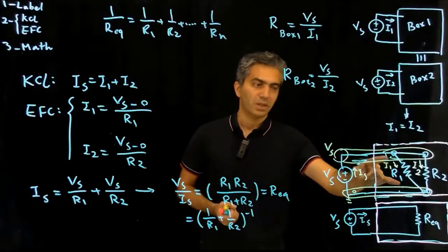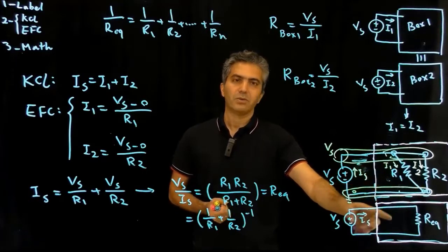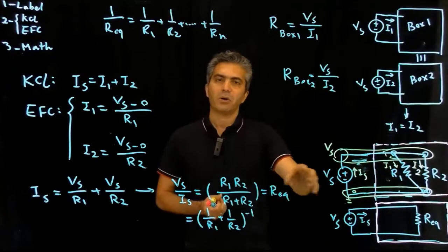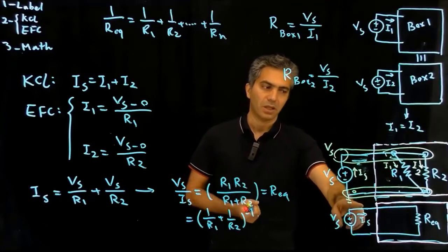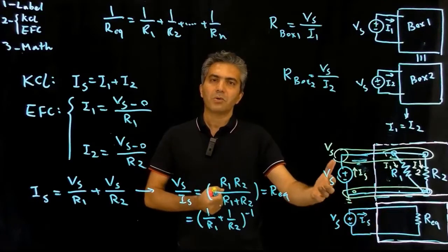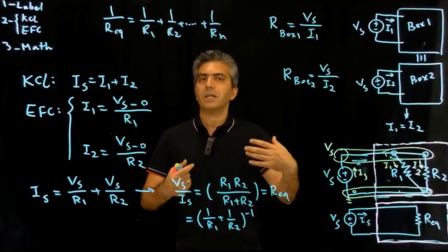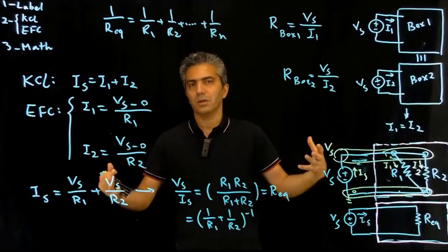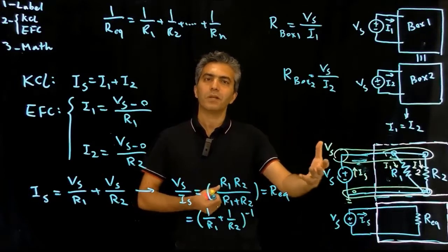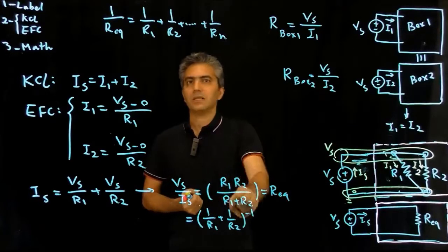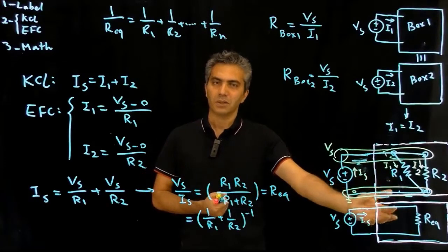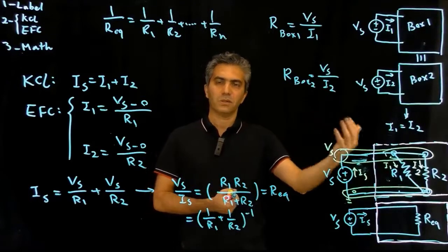So with this, now we know how to calculate the equivalent resistance when the resistors are in parallel to each other. We already know how to calculate the equivalent resistance when the resistors are in series, and we can use this knowledge to start approaching relatively complicated networks of resistors connected to each other and calculate equivalency for those circuits using these 2 techniques that we just learned about: equivalence of resistors in series and in parallel.